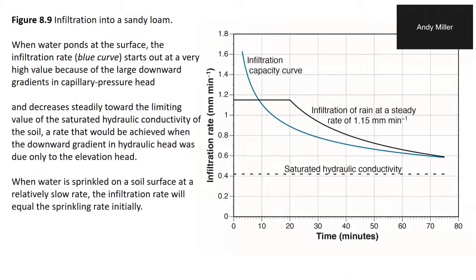What happens? What's the infiltration rate under those conditions? If the rain rate is not greater than the infiltration capacity, what is the infiltration rate? It's the same as the rain rate, because all the water infiltrates, right? So that's this case right here.